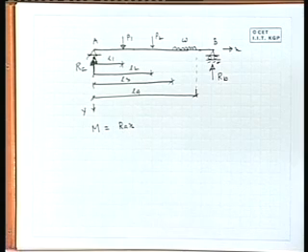Now, our objective is to get a common expression of bending moment. In that case, we will use the unit step function to combine different segments. Now, if it is 0 to L1, your bending moment should be your RA into X, right, or let me write the expression of M. M will be RA into X. So far, we are within L1, X is 0 to L1, this will be valid.